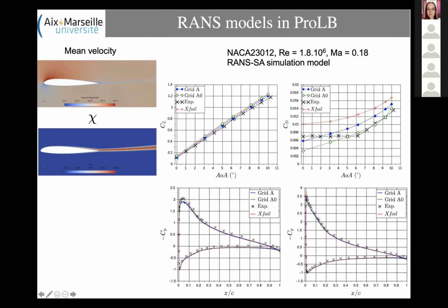You can see that for the lift, it's pretty accurate. And for the drag, we have two different solutions because, of course, drag of such a clean wing is very small, so computational errors are visible, but we are close enough to experimental data to use such data.